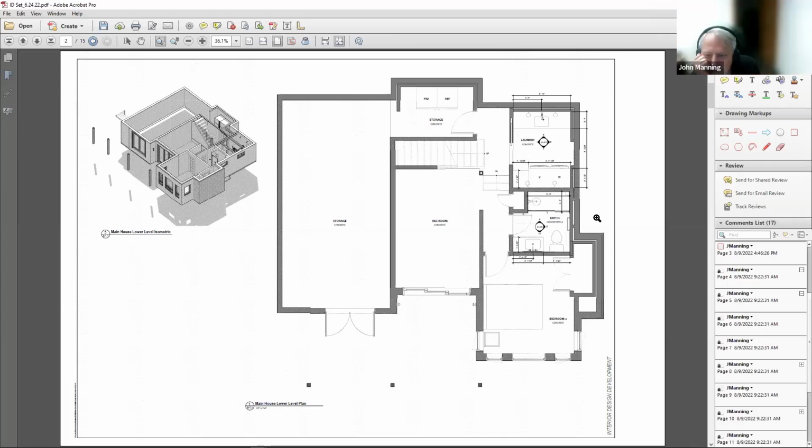It gets us away from what I consider the ideal piece of equipment, the Sycamore variable speed. The smallest unit there is 3 ton. If we added another 1 ton unit that could go here, that could handle just the second floor, that might work. And we go with a 3 ton variable speed to handle the lower level from the ceiling and the first floor up from the floor. So we could put a small 1 ton or 1.5 ton vertical unit here. And they're certainly a little quieter, being smaller.